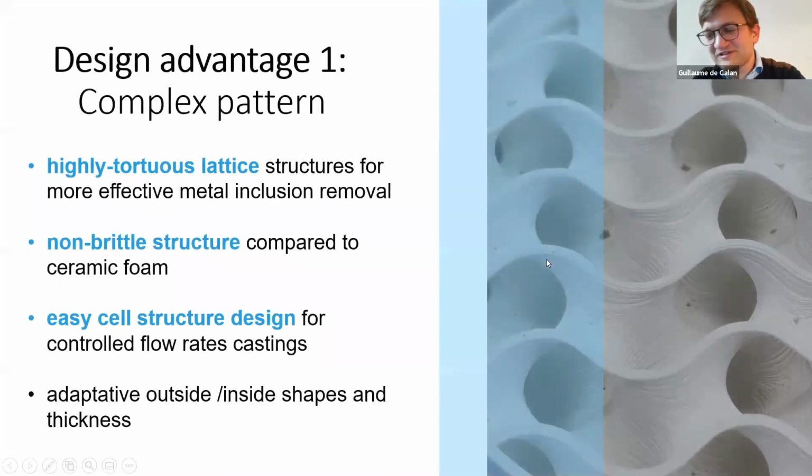So about polishing, that's one of the interesting things. Both with ceramics and metal, you have materials that polish really well. They have enough strength to be polished in industrial processes, and typically the process we used here is what we call tribofinishing, or tumbling.